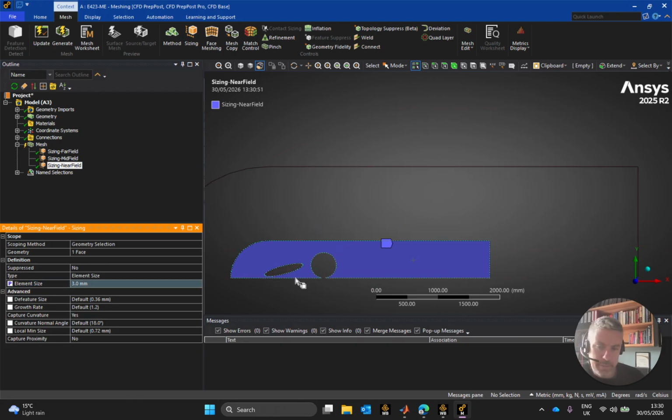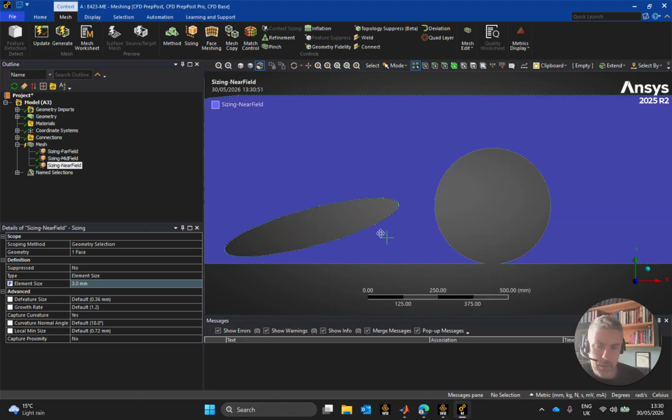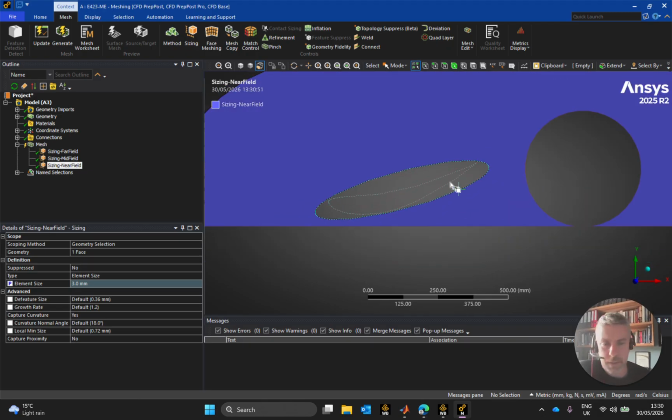I'm a wee bit all over the place here, so I'm going to stop and explain myself. When I rotate this, or stretch this in or stretch that out, I'm stretching this out into cells, and when I rotate this, I'm rotating this in against cells. That's going to skew them cells. It's going to throw the orthogonality off of them. The larger they are, the less likely the software might be to regenerate some of them cells, and the skewness will go up.